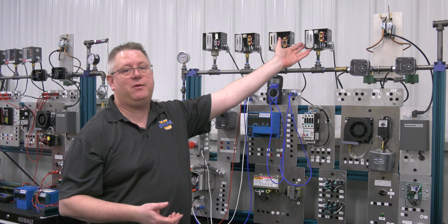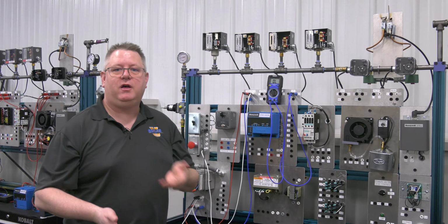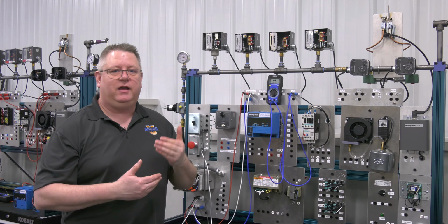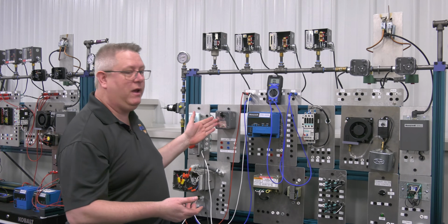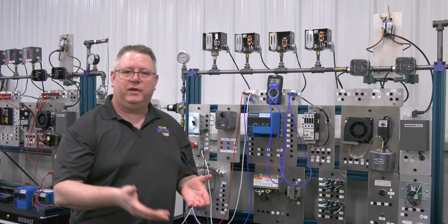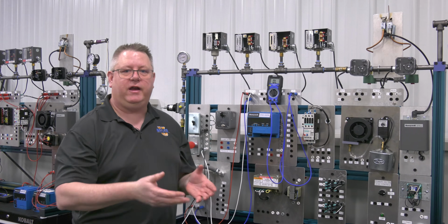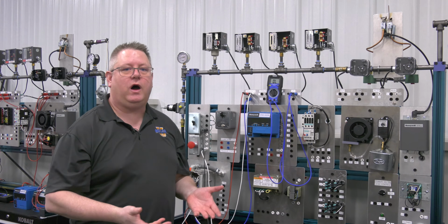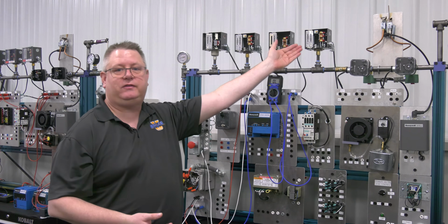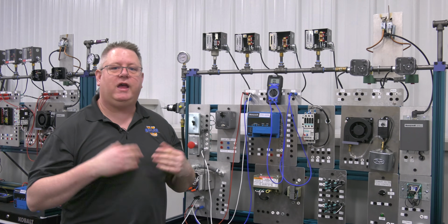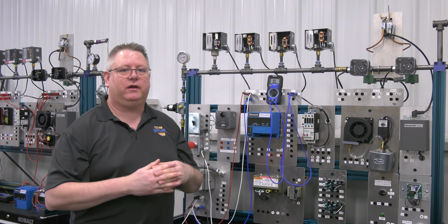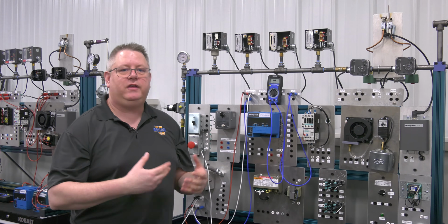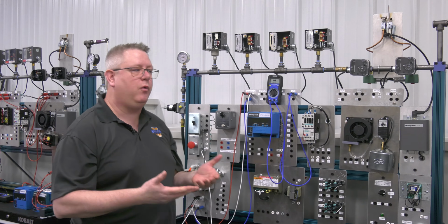Now, this is not the best tool for the job. The best tool to prevent that is a competent operator, putting the firing rate control in manual and warming the boiler and walking the firing rate up slowly as required. But it is necessary in many cases if we have boilers that start automatically by time clocks and things like that, because it will reduce the impact of thermal stress on the boiler.